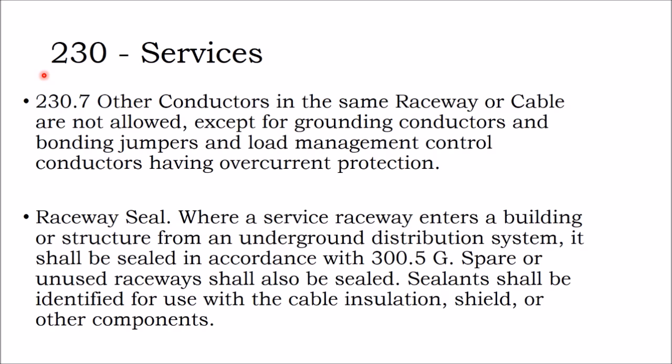What that says is if I'm establishing an electric service on my service cables, and this is not the utility service cables, these are really the service entrance conductors coming from our solar array, which are feeder circuits, or analogous to feeder circuits. If they function the same as feeder circuits, and we call them services instead of feeder circuits, well, what's the difference? They're going to have the same safety requirements.